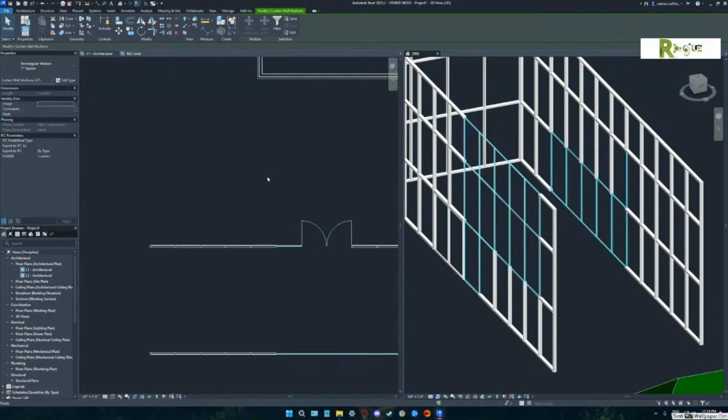And you'll see that all of those mullions will now be thin mullions. Okay. Does that make sense? Yeah. And the reason it didn't work on this side before is because it's not selected under not defined, right? That's correct, because it wasn't not defined. So therefore, those things say we want our mullions to be 2x4s because that's what it tells us to make our mullions as 2x4s. Right.